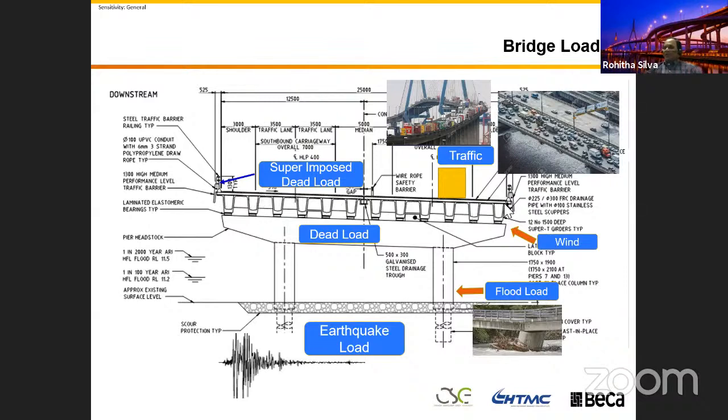After the bridge deck becomes a composite section, whatever you construct after that, we call superimposed onto the bridge deck. We call it superimposed dead load. For example, the bridge barrier, the deck drainage, and anything you build after the deck is hardened, constructed on top of or attached to the bridge deck, we call superimposed dead load.